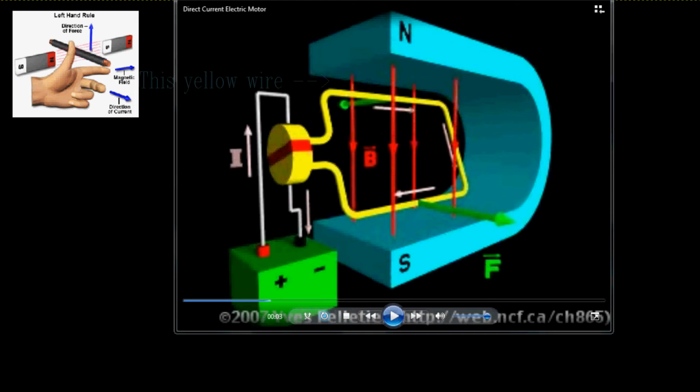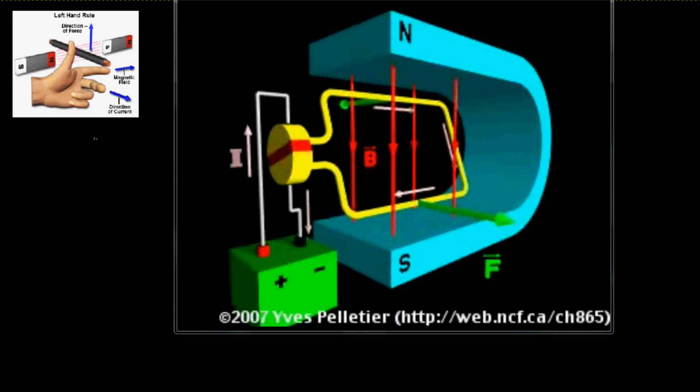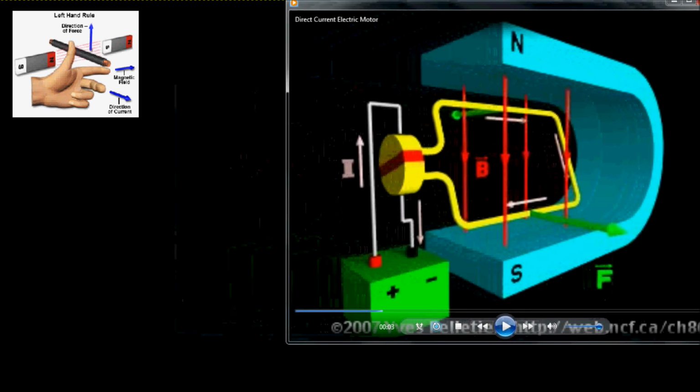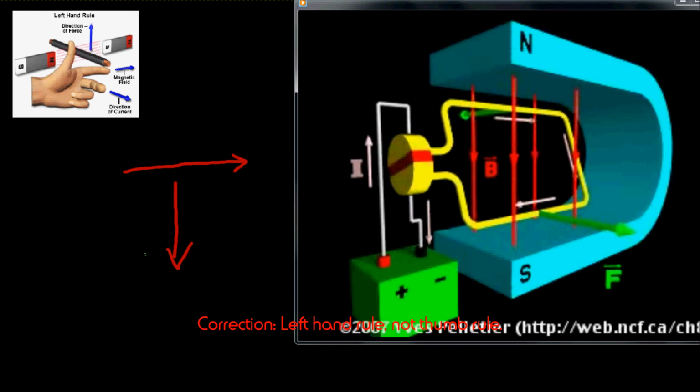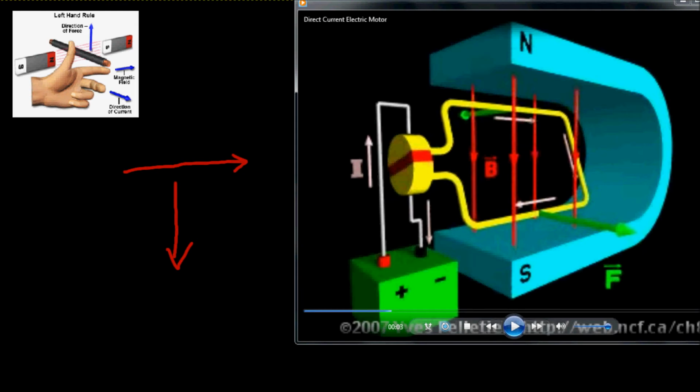Now let's just take this top part over here, the yellow wire which is on the top. Apply your left hand rule over here. Okay, this is your conductor going like this. Your magnetic field lines are going like this. That's how it looks. Now just apply this left hand thumb rule here. So your index finger points towards magnetic field, so it's going down. Direction of current is rightwards. So you can see that your thumb will be pointing away from you, which means that if you look at his green arrow here depicting the force, that's also going that way inside the screen.